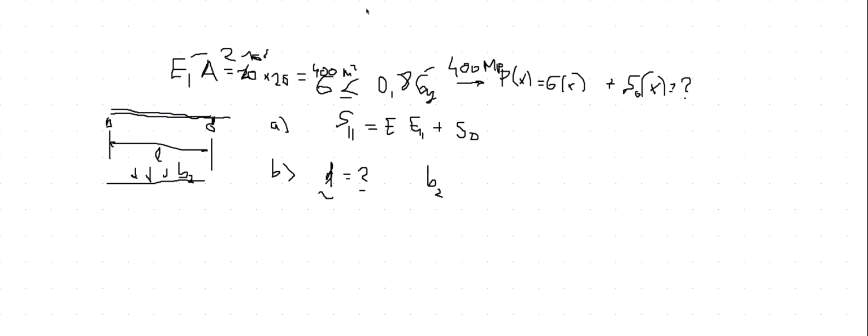And then what you want to produce, you can try different displacements to produce something where you don't have a maximum slope, which is equal to some kind of D max. D max could be, let's say, 0.2 L. So you're not really sagging too much when you're building a pedestrian bridge that you want to cross. You don't want it sagging too much under B2.